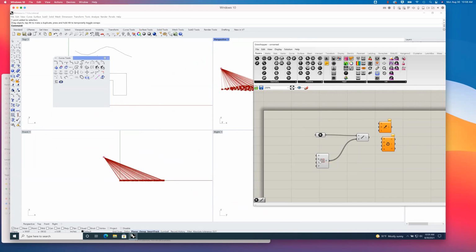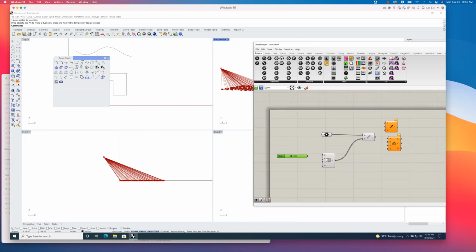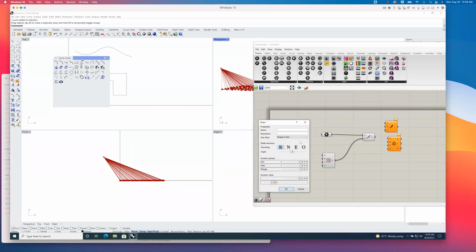Now let's take a look at some of these ingredients, right? Again, I can start to build in some numbers. So here we have the number of points to add. I went to the params tab, right? That first one, right? And number slider is one of those things that we'll use over and over again, number slider. I can double click on that label called slider, and it gives me the properties here. I can constrain this to integers, so just whole numbers, along with 0 and along with all the negative values of whole numbers. I can say minimum of 1, maximum of 800, right?